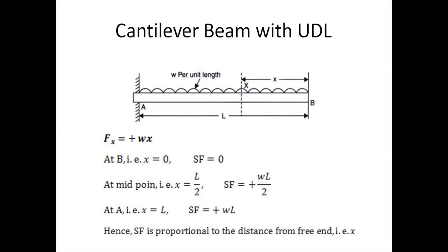So, clearly, the shear force is proportional to the distance from the free end, that is X. If the distance is 0, the shear force is 0. If the distance is L, the shear force will be W into L.